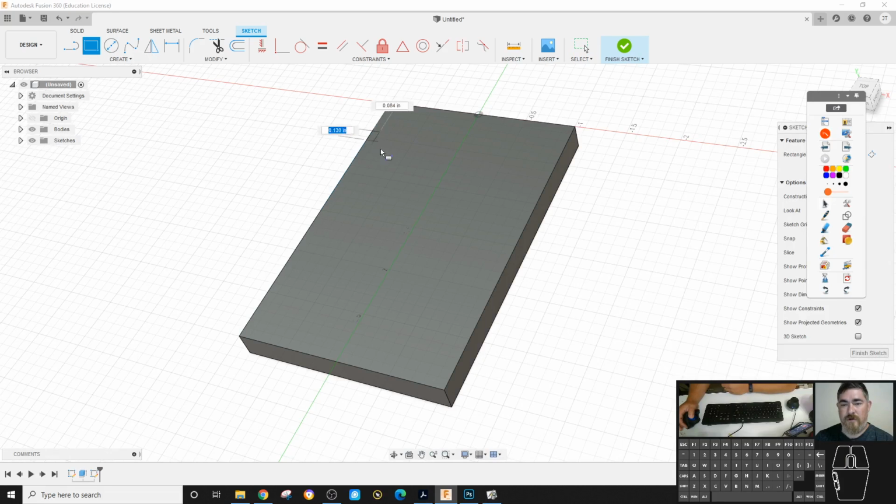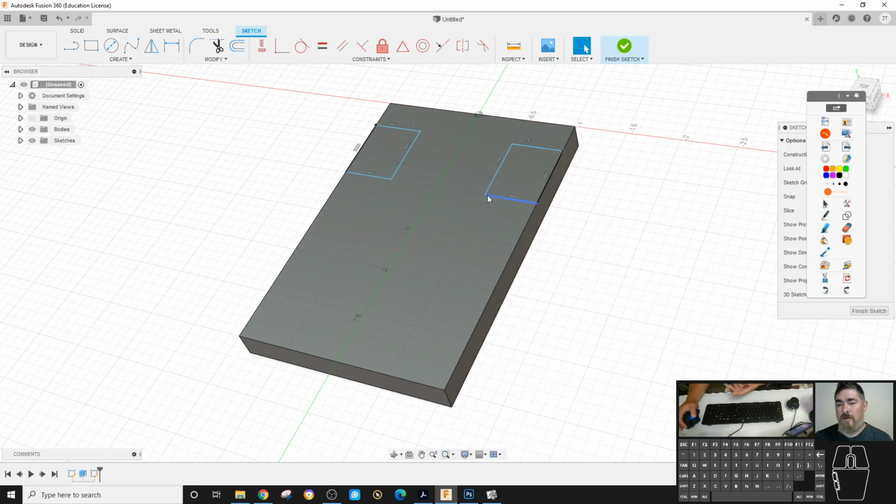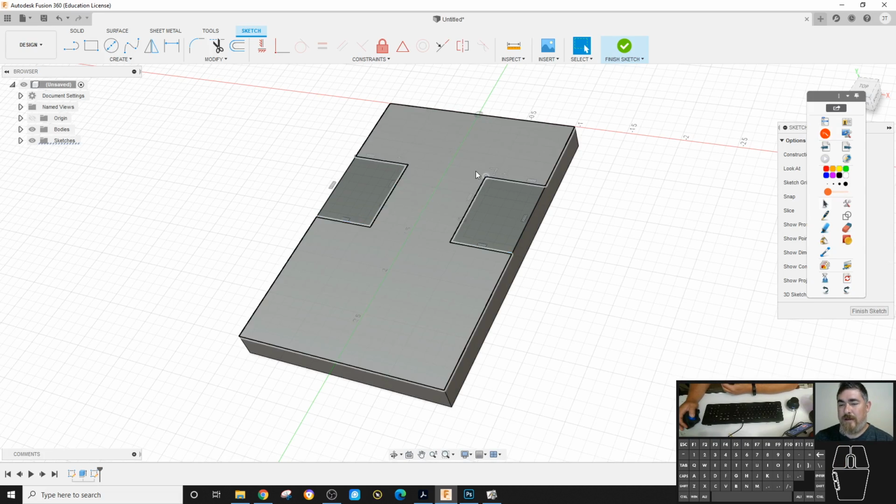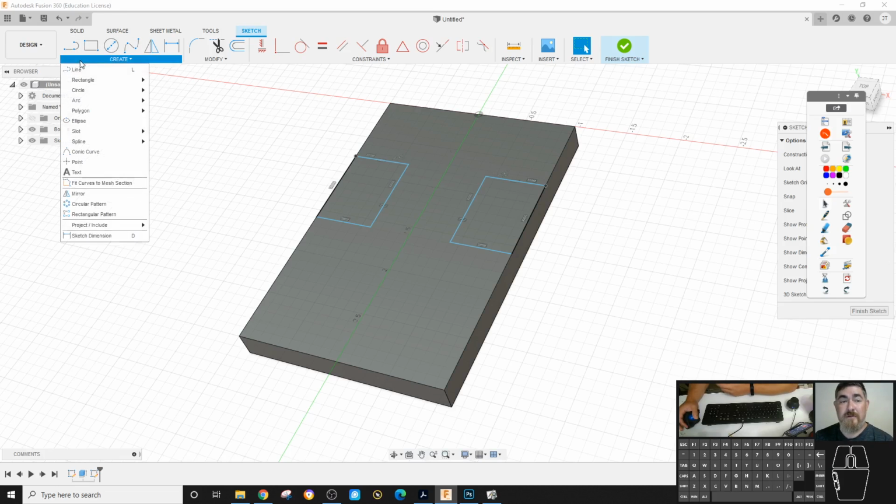And then I'm going to start from the edge, because I know that I want that to be on the edge. Make those 2 tops equal length. Make those 2 equal length. And then I can use my collinear to line up these 2 tops. And so now I can just grab points. So grab a corner, drag it around, and make sure it behaves the way you want it to behave. If it's behaving correctly, now it's time for dimensions. If things were going wonky, then maybe it's time to do something else.